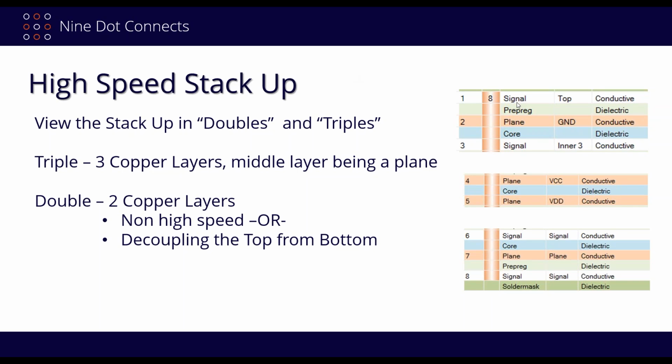So when you're dealing with high-speed design, you want to do things really in what they'll call triples and doubles. And you want them always to be an even number. So in the industry, you normally do not make a 7-layer or 5-layer board. You usually work in pairs, and you always want to try to keep the symmetry. You're always worried about warpages. You're also always worried about twisting as well. So symmetry helps with avoiding those type of issues in the fabrication process.